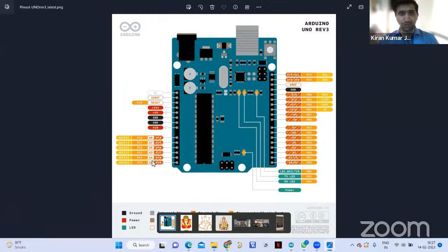So we have 6 pins over here. This is the Uno board, the microcontroller Uno. We also have a power supply section over here. You can see the 3.3 volt, 5 volt, and 2 grounds, and V in. V in is basically an input voltage to the board, which ranges from 7 to 20.